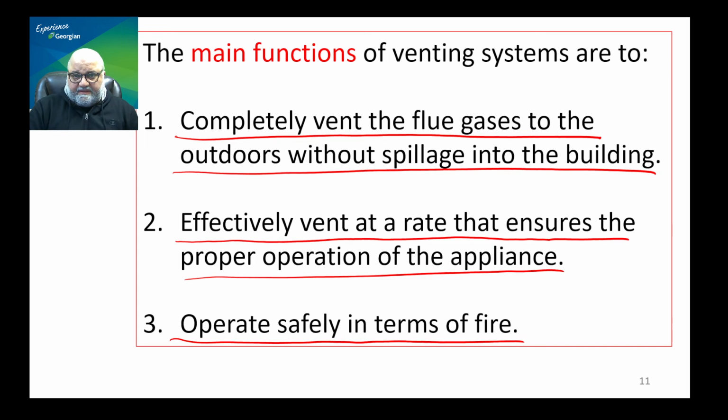So those are the three things that you always think about. Remove everything outside. Have the capacity that matches the appliance. And whatever you're doing, do it safely in terms of the venting temperature, and of course corrosion.